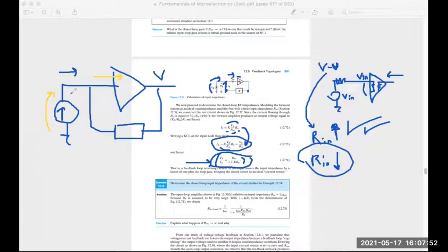And the way that all this current can go here is this impedance is small. So actually in this amplifier type, we want Rin to be small, right? So this feedback sensing the voltage and deploying currents back to the output basically helps our purpose. Okay. So feedback always helps our purpose. Just I am showing you how.